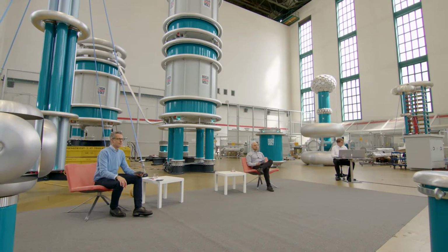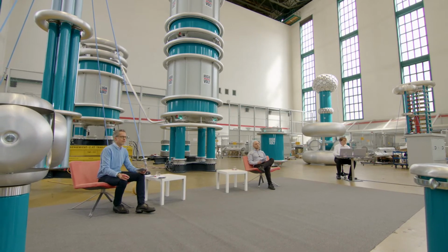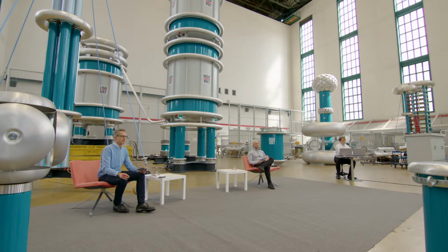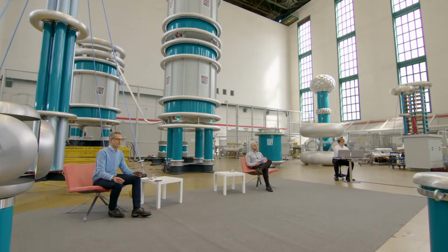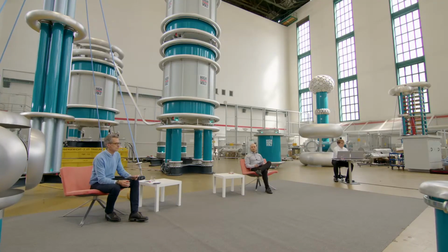Yeah, indeed. So partial discharge measurement can avoid that a failure develops and leads to a complete malfunction of the cable system. So it can be an indicator of there's something going wrong, to have time to react and to search for the failure part and to explain maybe the malfunction cable part. But when we measure PD, there is already something going wrong. Another point is also the aging condition assessment by maybe dielectric measurements. So how to get an insight in the cable dielectric before you start PDs. But this is another topic.